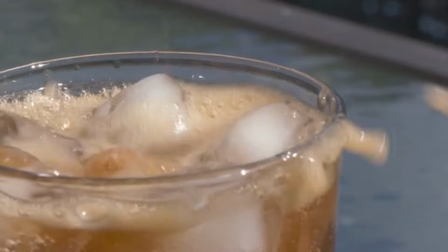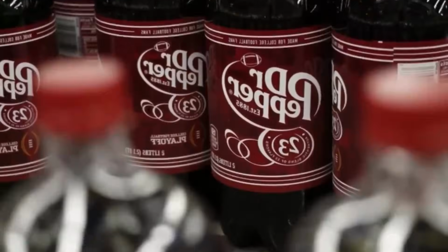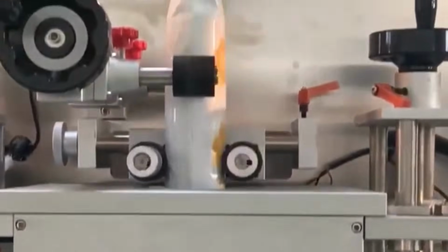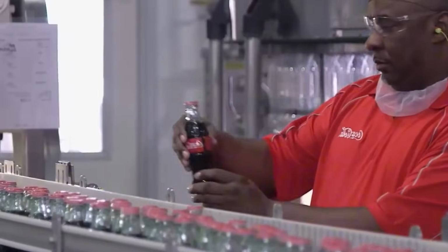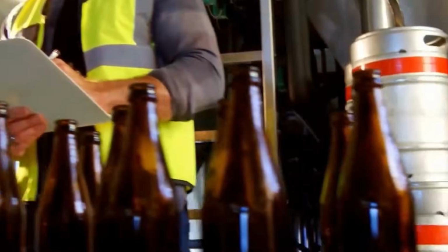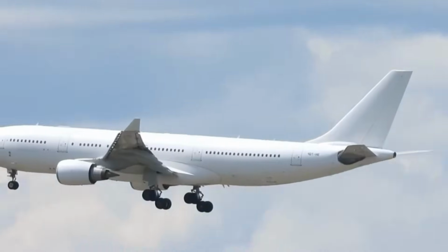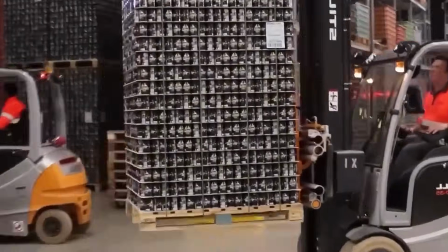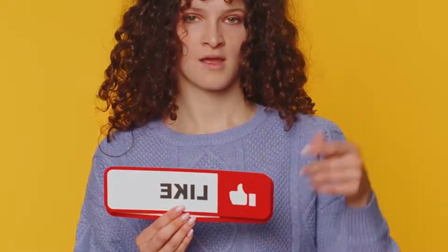The filling machine features multiple heads, typically between 40 to 120, arranged in a rotary configuration. Each head is fed from the pressurized carbonated beverage tank. As a container aligns with a filling head, it is clamped and sealed. Counterpressure is applied to prevent foaming. A filling valve opens and the product is gravity fed or gently pumped in. As the container fills, vent tubes displace internal gas to maintain pressure equilibrium. Once full, the valve closes and the container is released.